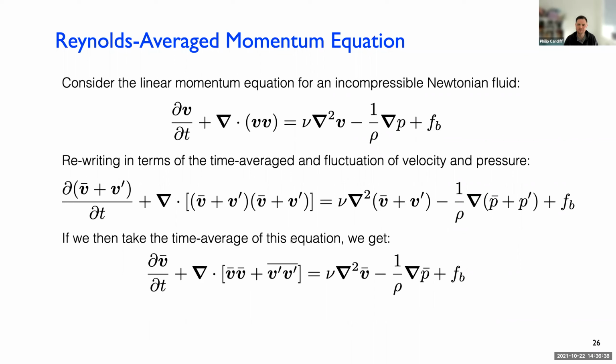If you don't believe that, maybe just generate two random cycles in Excel, random about 0 so their average is about 0, and then multiply them by each other and take the average. That average won't be equal to 0. Depending on where the peaks are, if they line up, you might get a very positive peak in the perturbation by the perturbation, but you might not get the same one on the negative side. So the average of a perturbation by a perturbation doesn't disappear.